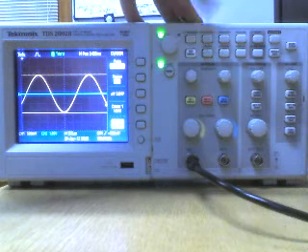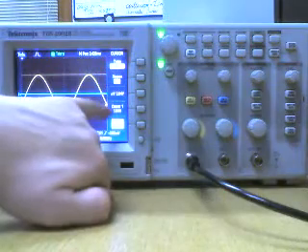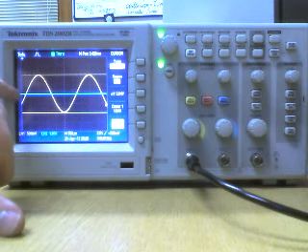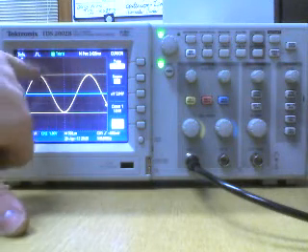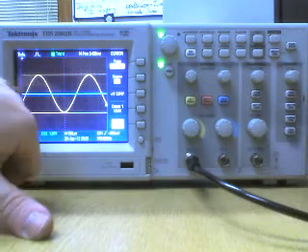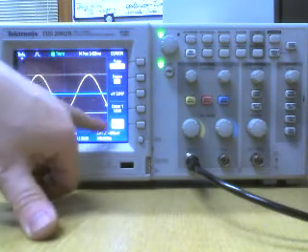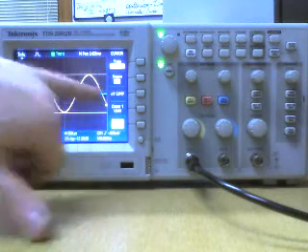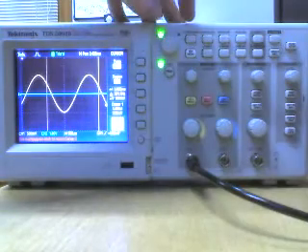So just when it's on its edge of the waveform, you've got a measurement of cursor 1 of 1 volt. That's from your 0, the ground, wherever you put your ground, to the top of your waveform. 0 to plus, cursor 2, 0 to minus. So 1 volt positive, 1 volt negative. That's 2 volts peak to peak. Very simple. And the same can be said for time as well.